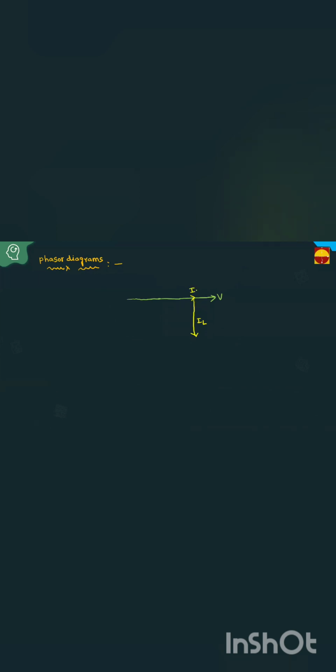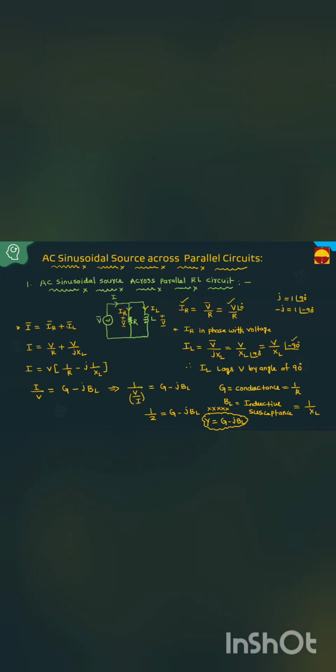This is IR and this is IL. This angle is 90 degrees. The angle is measured in the clockwise direction. This is clockwise, and this indicates the lagging. Then this is IR, this is IL. What is this? I equals the vector sum of IR and IL.